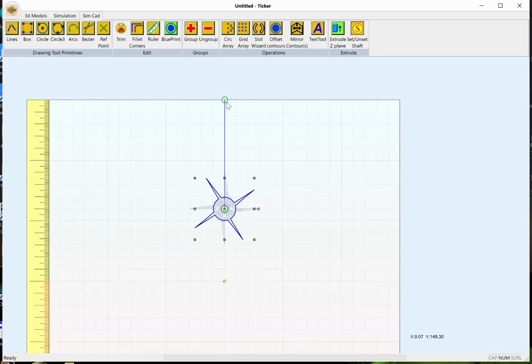Now you want a 90-degree angle from the hanging point of a pallet to this tooth on its release trigger. So you would want your ratchet to point at an angle of approximately here, so that whatever your locking pin was, it's 90 degrees from here to the tooth. In our case, however, I want as little slip as possible, so as an experiment, I'm going to go straight up from this tooth for our release pallet pivot.